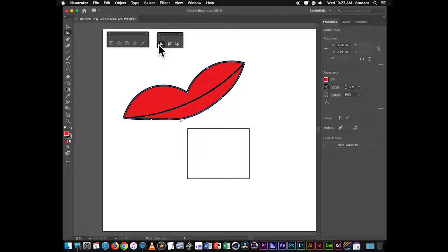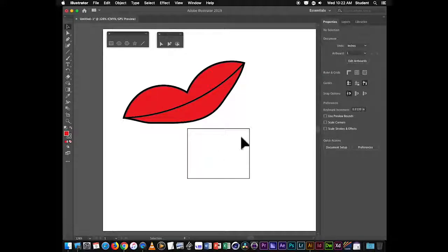This is the direct selection tool, the white arrow tool. So now you have the ability to start to move points around, and you can kind of take this and maybe extend it out, play around with the handles, things like that. And so you can go in and fine tune some stuff. But for the most part, Illustrator works with shapes, and you don't necessarily have to draw really well to create things. This box down here, when I select this box,